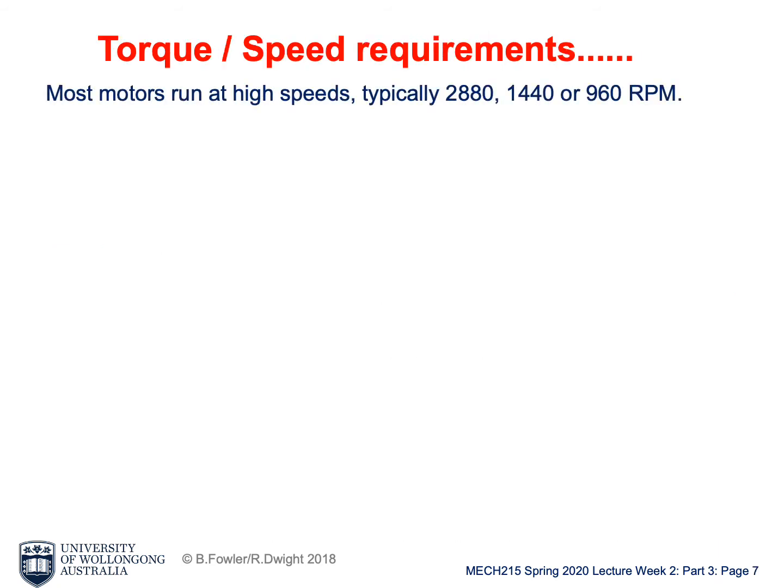Torque speed requirement where the motor is running at the nominal setting. So this is when the motor is running at the desired speed. One thing to be careful about, as we mentioned a few times, is that we can't really select a motor at whatever speed we want. The motors are designed based on those nominal speeds.